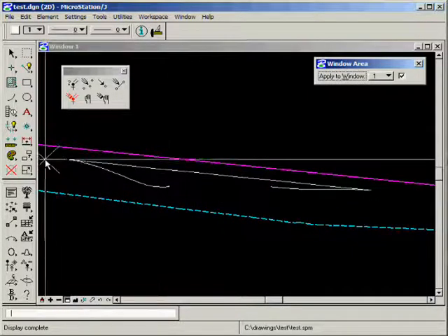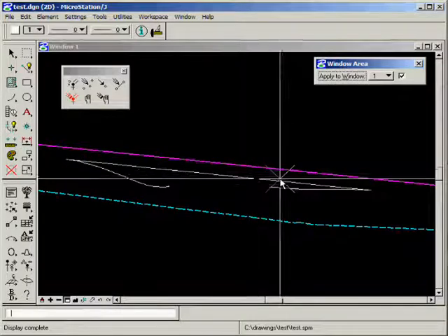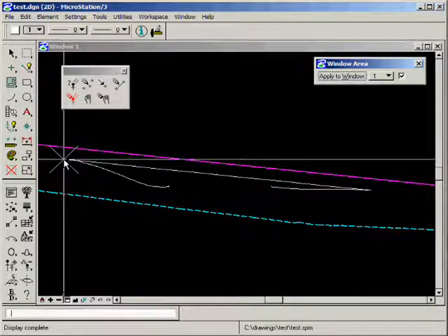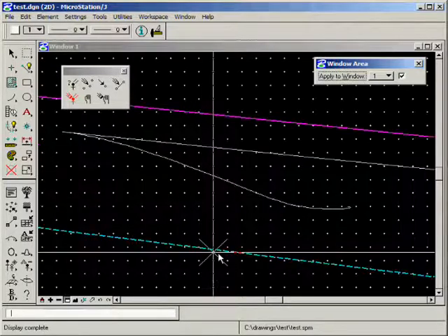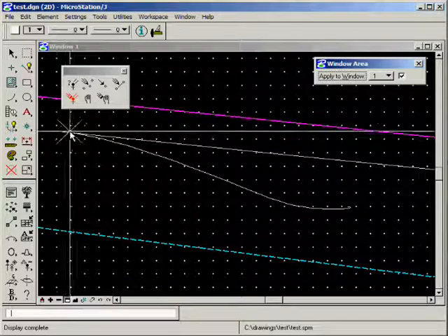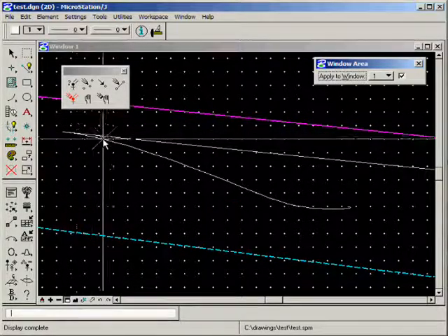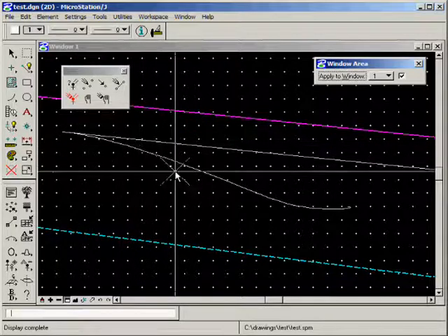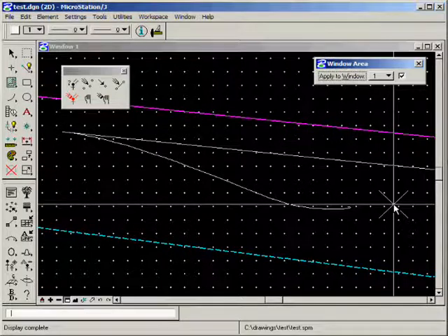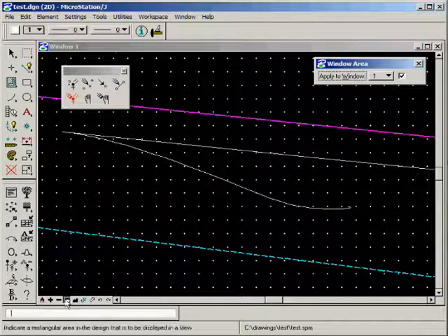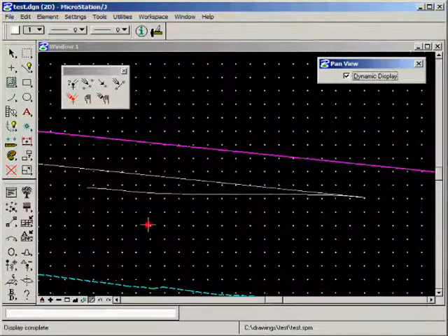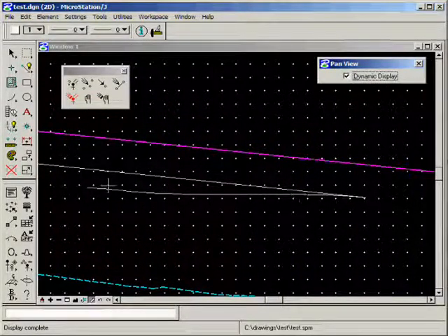Okay, what we're seeing is the edge of pavement as it comes through the intersection of the main street. This is the shape of the fillet superimposed, where it came out tangent to the edge of pavement of the main street and warped and transformed itself to drop its water off onto the side street. And likewise, this is the other turnout on the other side of the street.